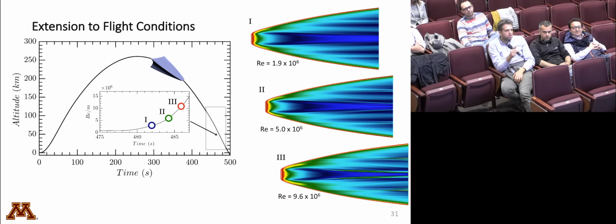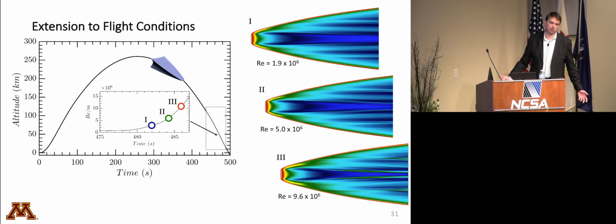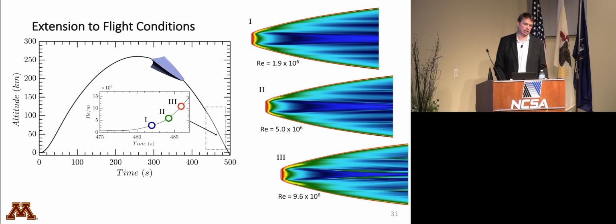No, and it's also the material properties, but there are catalytic effects for oxygen even at Mach 10 conditions. So at Mach 10 you would have to study chemical reaction. This is perfect gas. All the analysis that we've done so far has been perfect gas. We do need to. I don't think there's going to be any oxygen dissociation, but there could be some vibrational excitation under these conditions. But again, it's only 7.3 or something like that. And you have this very small stagnation region. It's probably not going to be a big difference between vibrational excitation and just perfect gas. But we will look at that and verify that that's actually the case.